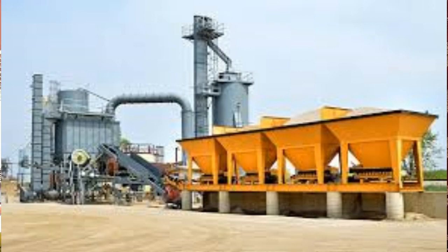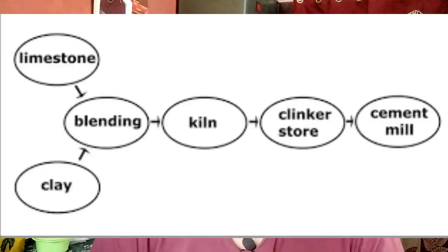And the next point is, what are the 3 components of cement? Lime or calcium oxide, CaO, from limestone, chalk, shells, shale or calcareous rock; silica, SiO2, from sand, old bottles, clay or argillaceous rock; alumina, Al2O3, from bauxite, recycled aluminium, clay. These are the components of cement.